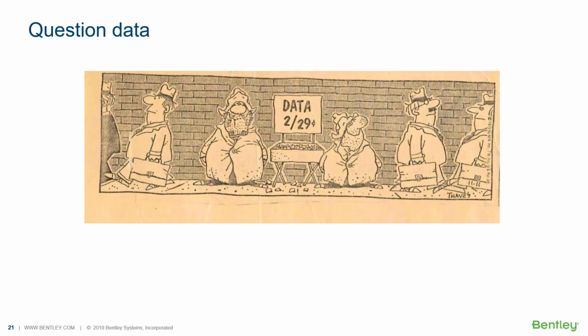One thing you've got to worry about is, if you're getting data, question the data. Sometimes the data is just inconsistent. It just doesn't make sense. How could the wet well be going down when the pump is off? You get these kinds of things, and something's wrong with our data. You've got to question it, because when you're working with data like this, trying to calibrate the model, the most fundamental rule is summarized by this little acronym: garbage in, garbage out. So you've got to really look at the data and question how good it is.